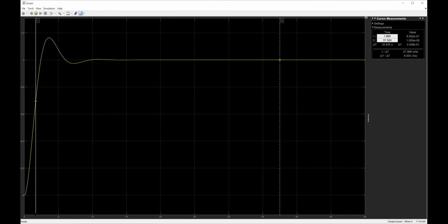It tells you that this time is about 0.15. So it's actually 1.65. So the time constant of this system is 1.65, when the system response is 66.6%, and I need to be super careful. Yes, this is close to 66.6%. My time constant is 1.6. Everyone understood the concept of time constant?